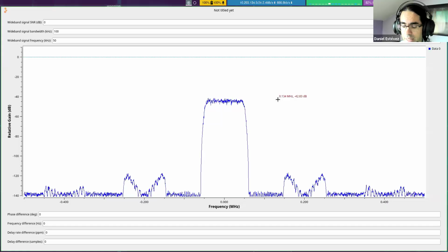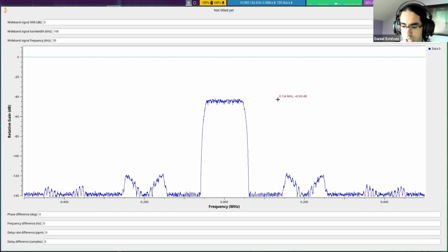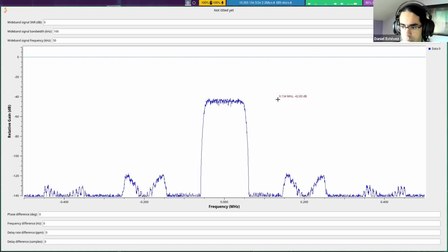It's also affected by the change of delay versus time. So that change of delay versus time is what causes a change of frequency, or apparent change of frequency, in the carrier wave, which we see as a Doppler shift in the signal. And then basically what I'm saying is because this delay is changing over time, the Doppler seen by each of the antennas is different.